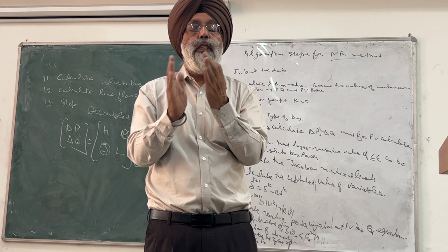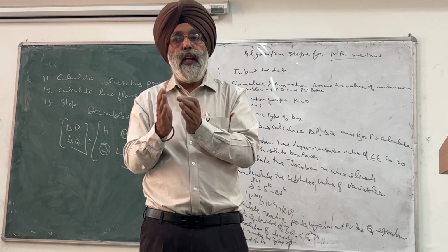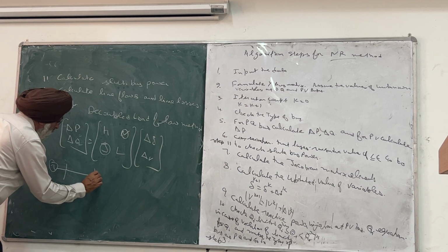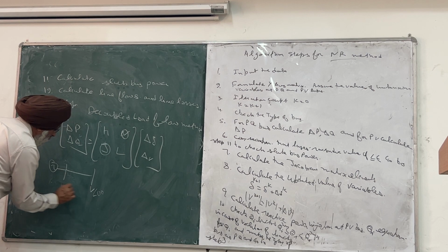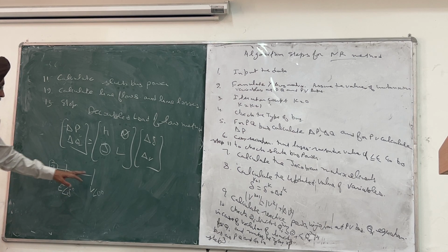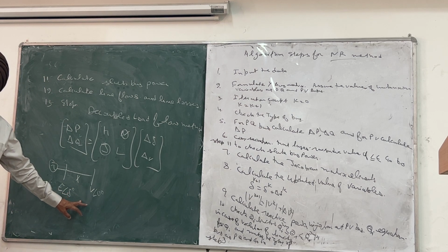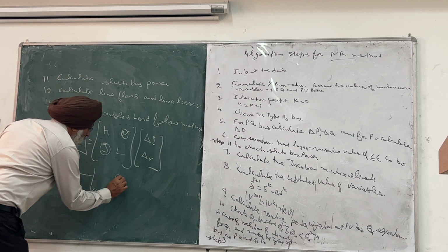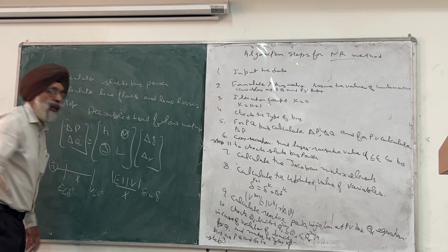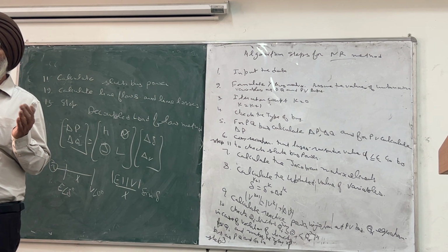It means the power which is delivered, the power which is transferred from one side to the other side, is equal to EV divided by X. Let us suppose it is V and it is at angle E. So if a generator is supplying the power, we have some reactance X. And this transmission of power is given by EV divided by X sine of delta, and delta is the angle of the rotor.